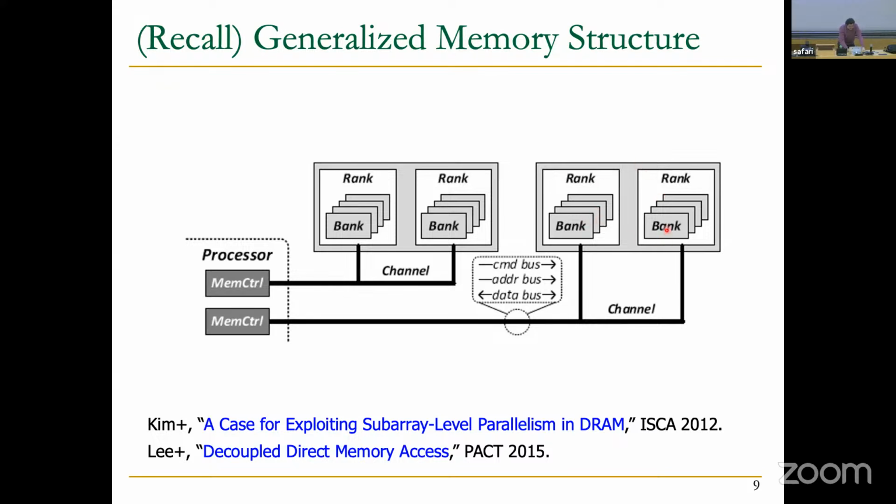And I'll just make another remark here. You cannot have a ton of memory channels to improve your system throughput or memory parallelism because each connection will cost you some pins. And pins are very expensive. You cannot very easily have 1 million pins. And because these will go outside the package over the PCB in a system where you have different electrical characteristics to basically satisfy, it becomes difficult. And they require a lot of area in your processor chip as well. The more pins you add, the more area you need to control this memory chip.